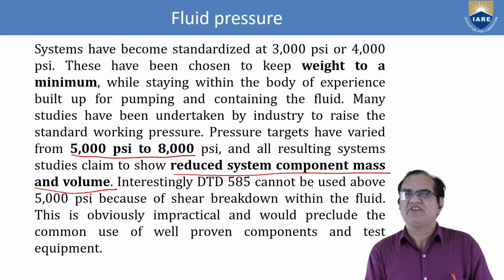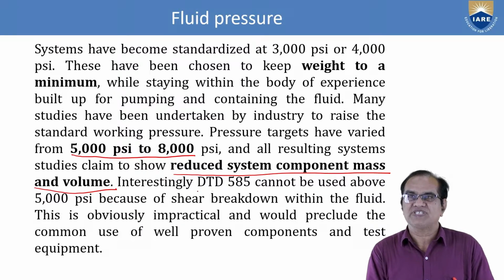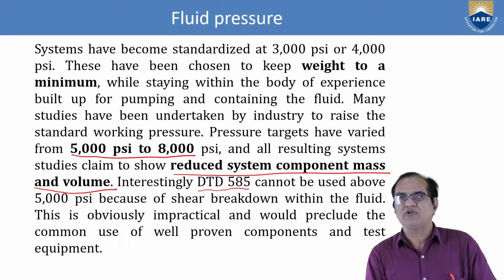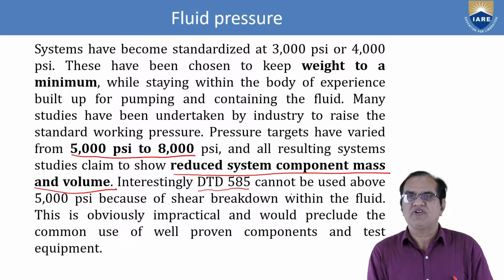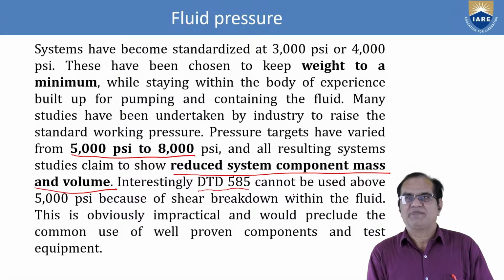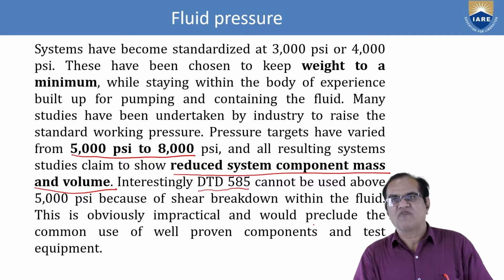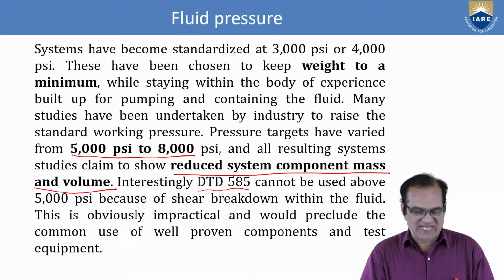Interestingly, DTD 585 cannot be used above 5000 psi because of shear breakdown within the fluid. So in the fluid itself, the breakdown will take place. This is obviously impractical and would preclude the common use of well-proven components and test equipment.